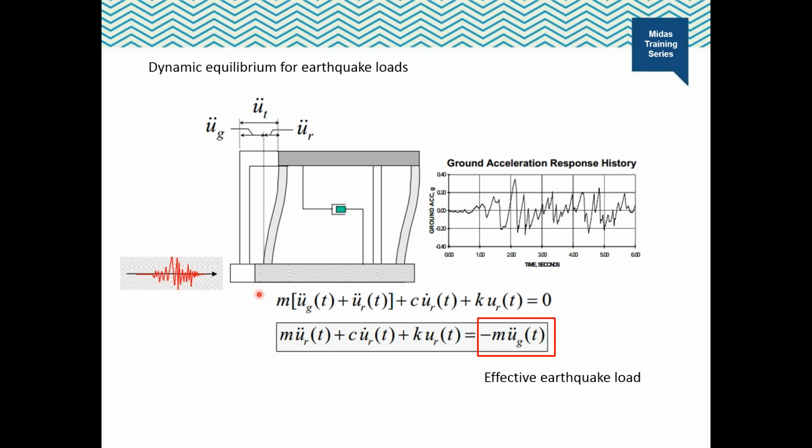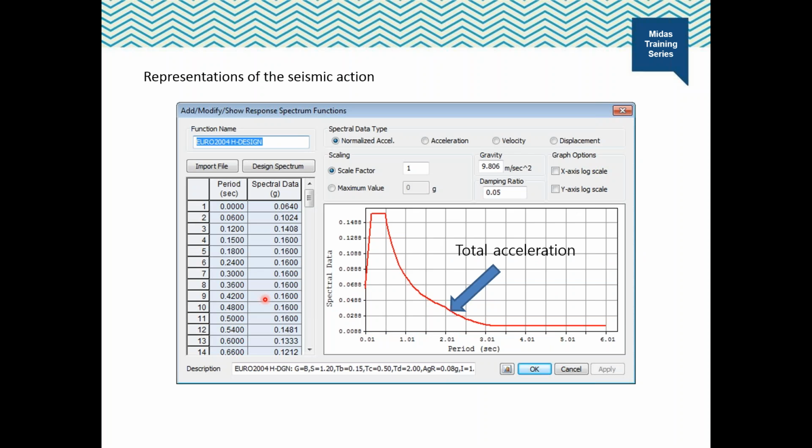Do you remember the equation of dynamic equilibrium for earthquake loads? We learned that total acceleration is the sum of ground acceleration and relative acceleration, and the total acceleration generates inertia force. The acceleration given in the response spectrum corresponds to the total acceleration, not relative acceleration.